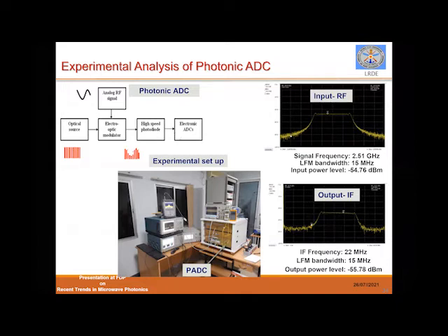And if you see, you will be wondering why I have written electronic ADC. I don't know how many of you are exposed to photonic ADCs. In the open literature itself, different types of photonic ADCs are there. We can do sampling in the photonics domain and quantization in the electronics domain, or sampling and quantization both in the photonics domain, and like that with different combinations.